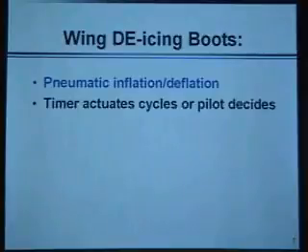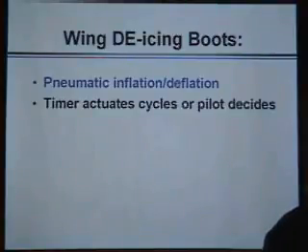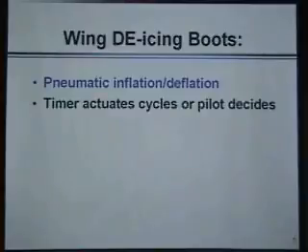Once you get the ice cracked and the relative wind blows the ice off, you have to turn off the boots and wait for the ice to form again. So you may run it for about a minute, and then after the ice is gone, you wait a few minutes for the ice to build back up, and then you've got to turn it back on again.